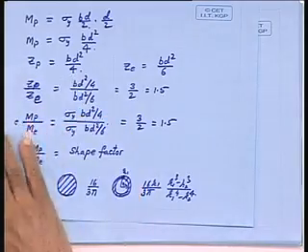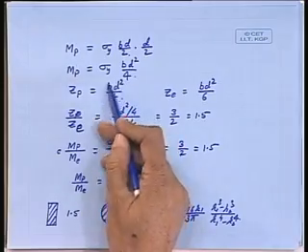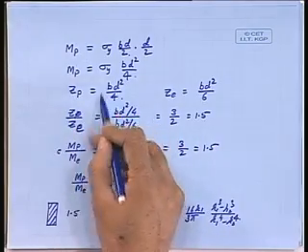So if we try that and say what is the shape factor, then the value will be in a different fashion. Okay. So the section modulus of the cross section in the plastic condition has to be calculated on the basis of how you are dividing the cross sectional area into two parts.